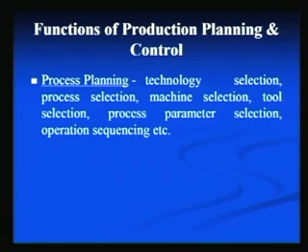So, basically when we go for process planning, we should try to use a tool which is available on the machine under consideration and which can be used without any changeover. Another important aspect to be covered in process planning is process parameter selection. Here, process parameters, for example in the case of a machining operation, may be cutting speed, feed and depth of cut, while in the case of a welding operation this may be the current, voltage, etc. of the process. So, we have to select appropriate machining parameters or process parameters for the execution of the process which we have identified earlier.